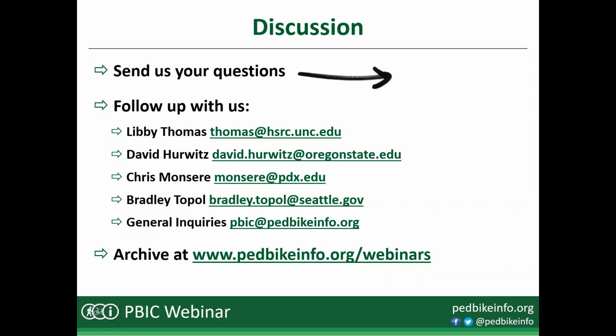And I also think that just from a pedestrian comfort and usability perspective, I'm a big fan of just pedestrian recall. Just make it cheap, make it simple. With ADA, pedestrian push buttons are becoming more necessary, and so you can still install those and leave it on pedestrian recall, and the push button can activate your audible and vibrotactile warning that the pedestrian signal is coming on.